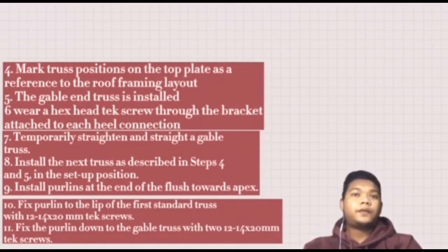About a third to half the length should be removed from the sling. At no time should the angle on the sling leg be more than 60 degrees. For a roof span of more than 9,000 mm, the screw bar or strongback will be used to prevent warping and damage to the truss.